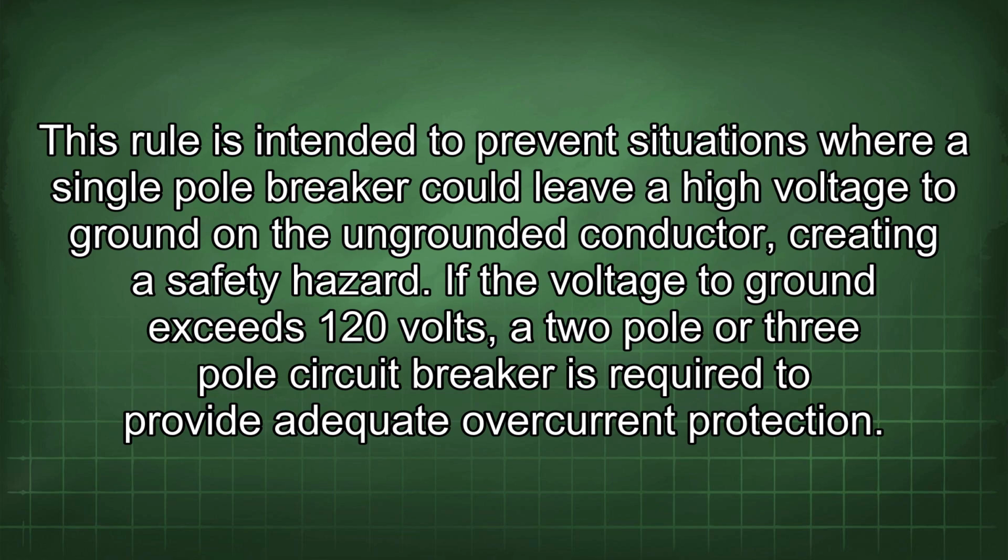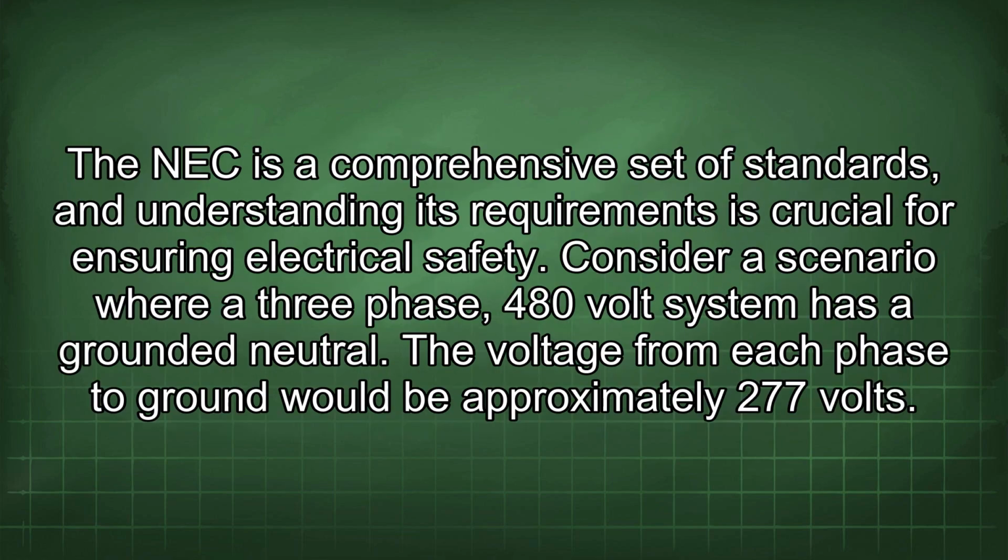If the voltage to ground exceeds 120 volts, a two-pole or three-pole circuit breaker is required to provide adequate overcurrent protection. The NEC is a comprehensive set of standards, and understanding its requirements is crucial for ensuring electrical safety.